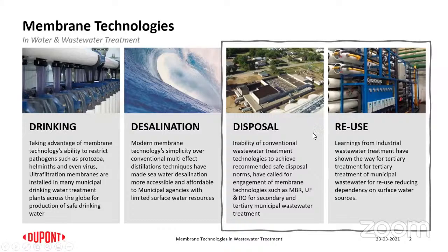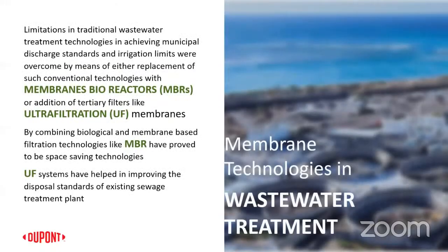Of late, you would see that the water quality requirements have been really pushed high. So in wastewater treatment, traditional technologies, I would name a few, like aeration processes, like activated sludge processes, which have their own limitations. Of course, they are robust, but they have their own limitations in achieving the disposal quality.